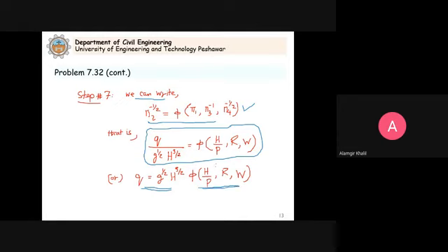A function of the coefficient of discharge, that we determine experimentally. You see, you study fluid mechanics 2 lab, so triangular notch, rectangular notch, for example, you determine coefficient of discharge experimentally. But at least from dimensional analysis, we know that it is a function of the Reynolds number, the Weber number, if surface tension is significant, and this ratio h by p. And this is actually what we studied.